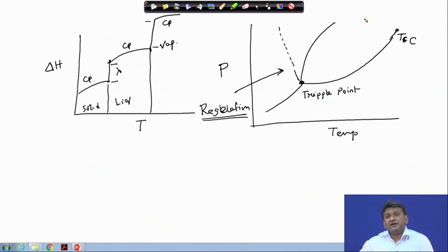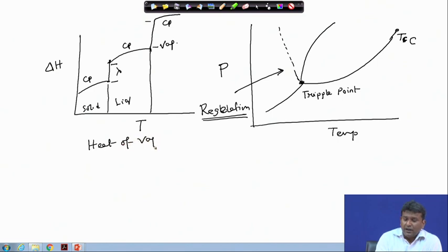Heat of fusion, unfortunately latent heat of fusion, there are no analytical ways to have a first approximation. So, you can't do that. Of course, please do also highlight that many times there are phase transitions within the solid phase, like the ordered-disordered transition, or martensitic transition, or ferromagnetic to paramagnetic transition, and so on, which are not very important, but a little bit of flavor of material science comes in. So, the last thing that remains is the heat of vaporization.